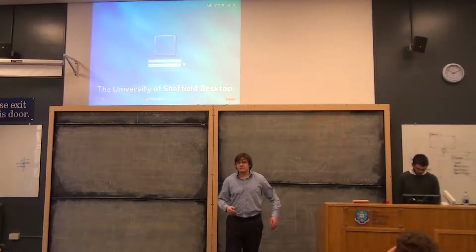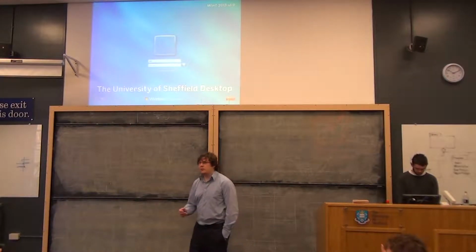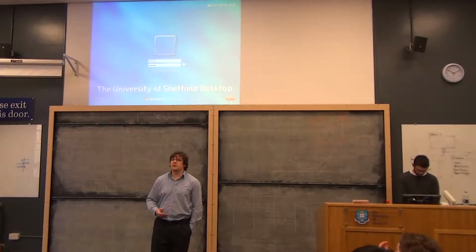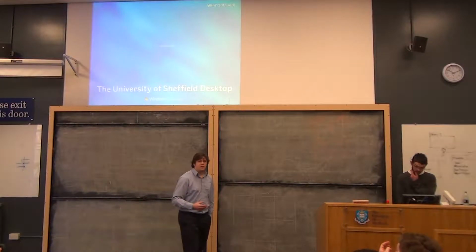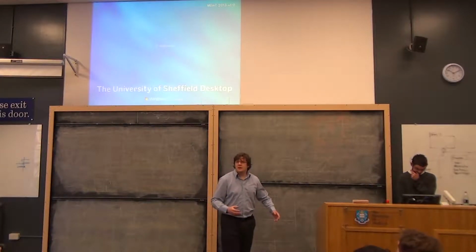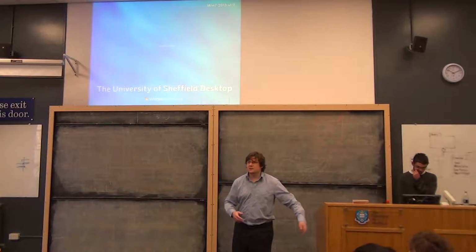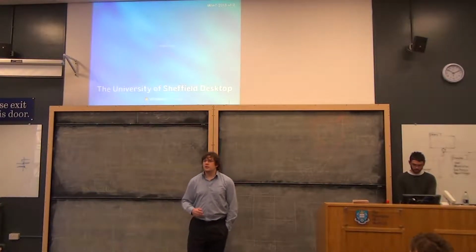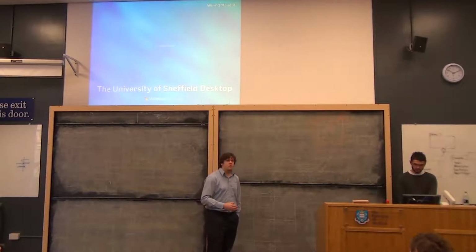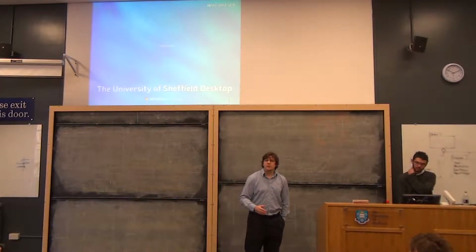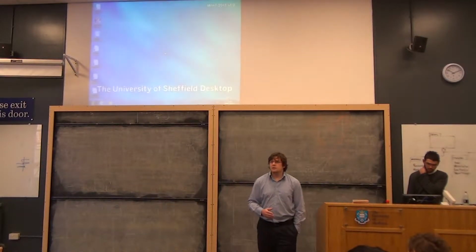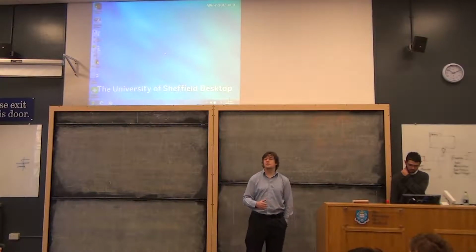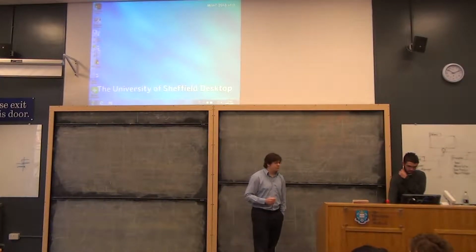So if I had some tiny little bench power supply and I put 0.1 ohms on it, its voltage would probably collapse because it couldn't supply that current. If on the other hand I had an enormous three-phase system the size of a telephone box or something, it might be able to drive that load, no problem. The question of making the load invariant is not always possible. There are certain limitations, but some circuits we can use to make the power supply more or less unaffected by the load.